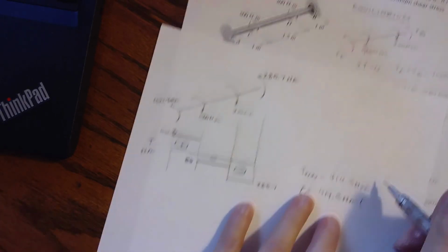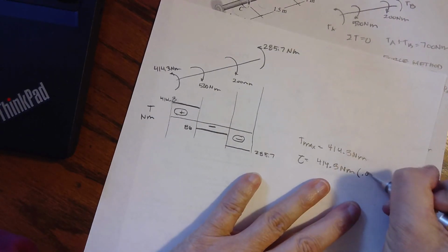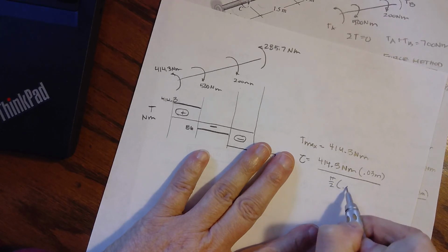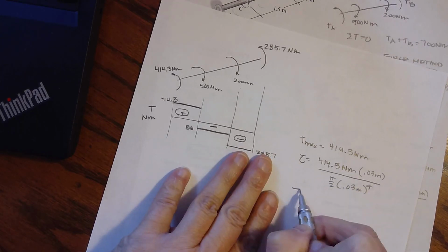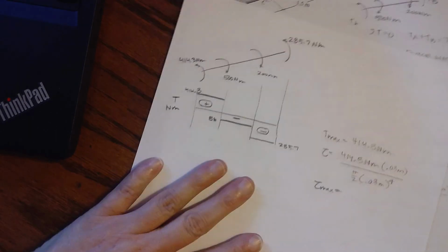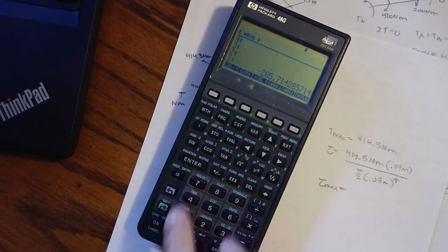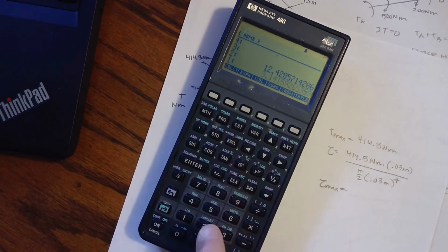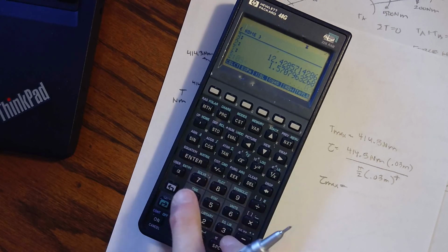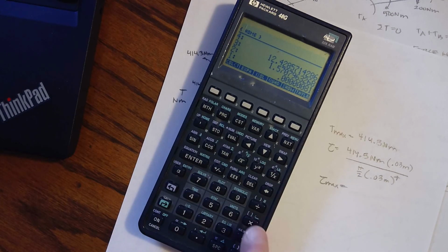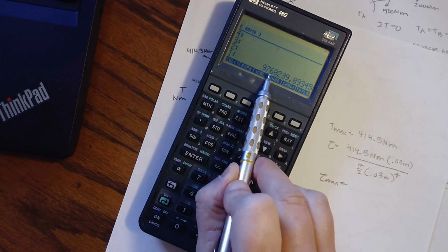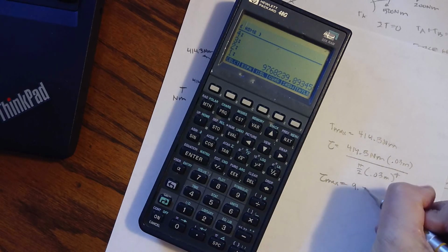And c comes from the radius. It was a diameter of 60 millimeters, so my radius is 30 millimeters, which is 0.03 meters, divided by its solid, pi over 2, 0.03 meters to the fourth. So that maximum shear stress is going to be 414.3 times pi over 2, divided by 0.03 meters to the fourth, times a large number. 1, 2, 3, 4, 5, 6. 9.77